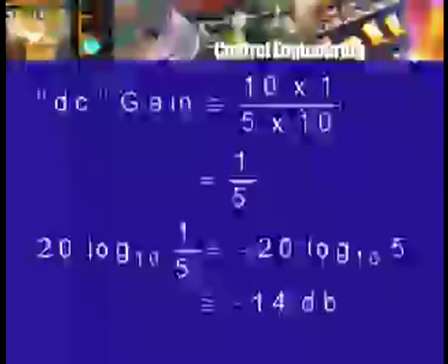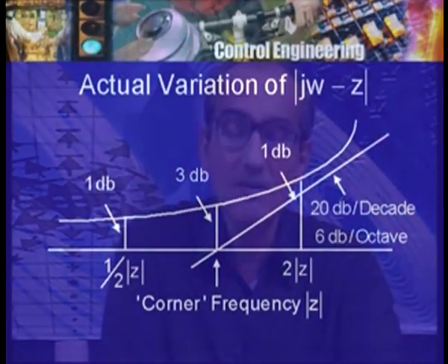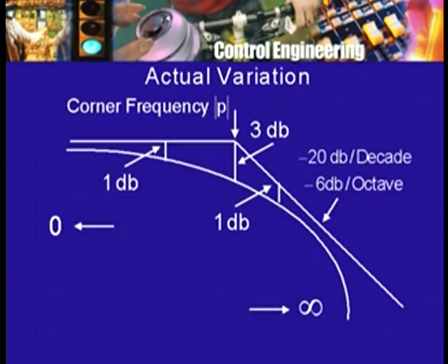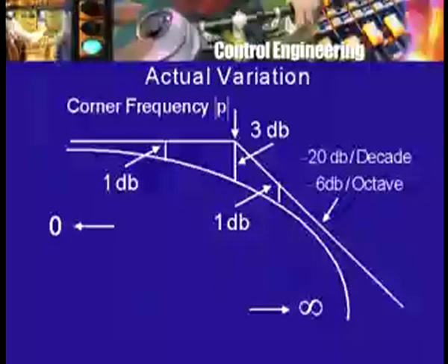Now, whether it's a pole or a zero, the asymptotic approximation for low frequency, as we have seen earlier, for a zero it is a horizontal line of some value. For a pole, it's again a horizontal line of some value, depending on the pole or zero location, right? So when I add them up at the low frequency end, I am simply going to add these horizontal lines which are at different levels, add or subtract.